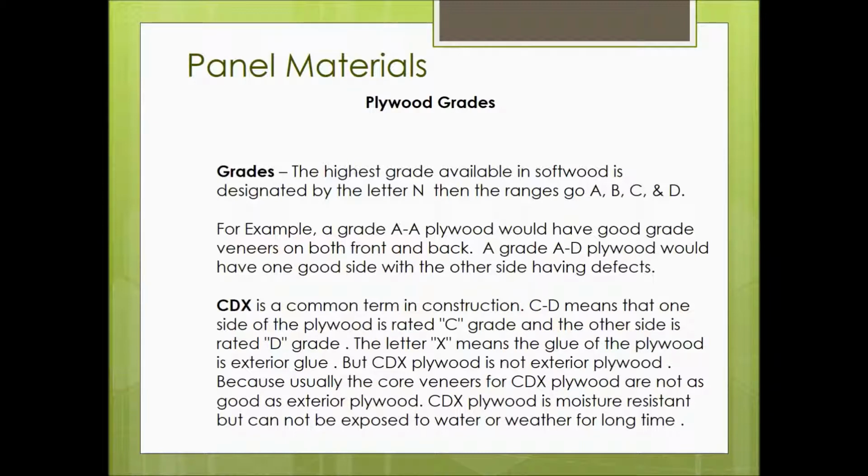Another type of plywood, which is CDX, is CD plywood, but it's also treated with an exterior type glue. It's not exterior plywood. I wouldn't use this in any kind of application that was going to be outside long term, but it is more durable with regard to being exposed to moisture than normal plywood.